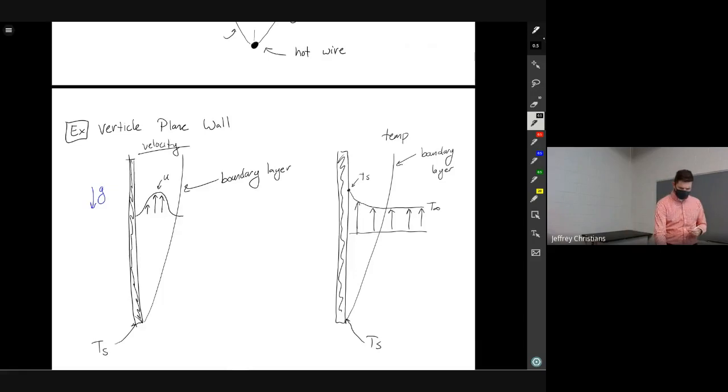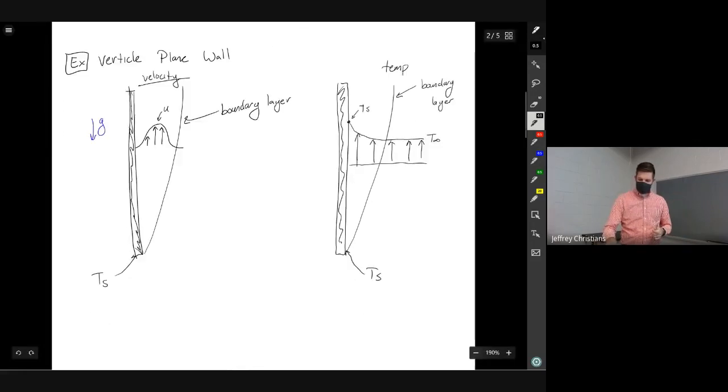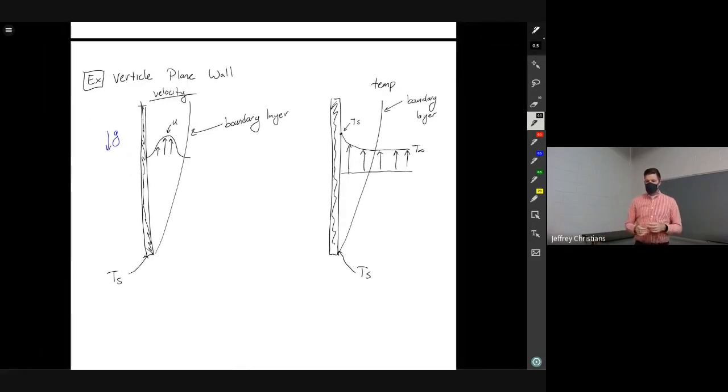So what's governing our flow in this case is buoyancy. The buoyant forces arise because the hot fluid is rising. So our flow is driven by this thermal expansion. You can maybe see from the temperature boundary layer on the right, we're going to have a little bit more complicated dynamics than for something where we don't have density gradients playing a role, because we have differing forces right near the wall.